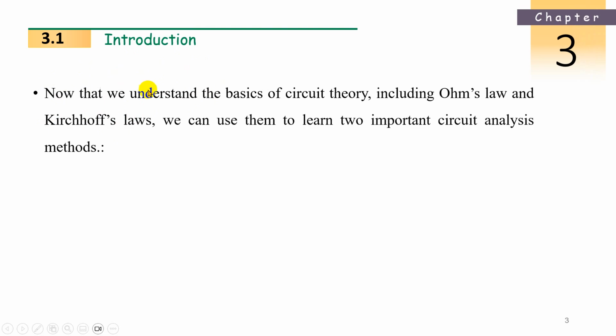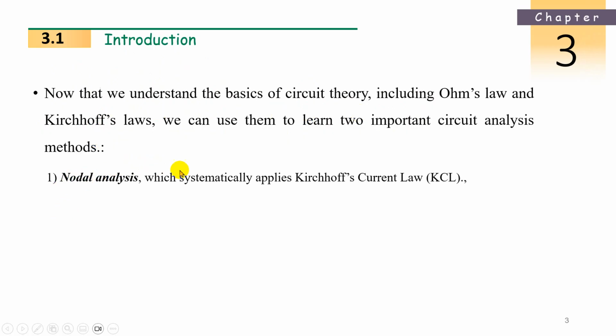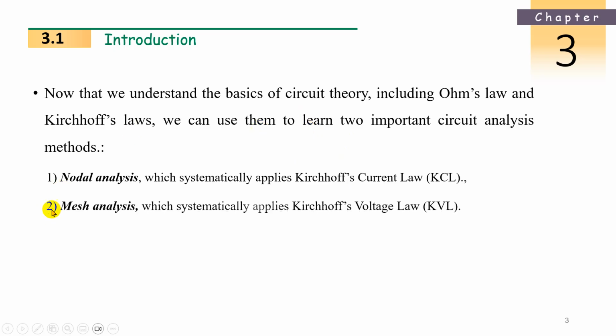Now that we understand the basic circuit theory, including Ohm's law and Kirchhoff's laws, the current law and voltage law, we can use them to learn two important circuit analysis methods. One is nodal analysis, which systematically applies Kirchhoff's current law, because at a node we mean current, so Kirchhoff's current law. Second, mesh analysis, which systematically applies Kirchhoff's voltage law.